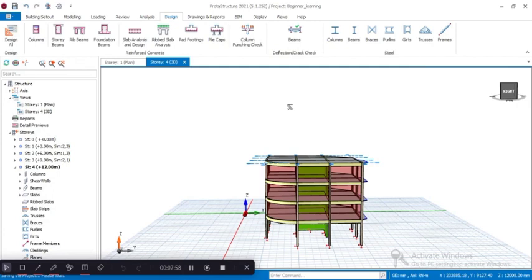This is independent of the general building analysis and can therefore be carried out before or after the general building analysis. To use the moment coefficient method, it is important to set all the slab types correctly in accordance with the tables in BS 8110. This can be done automatically in batch mode by right-clicking on the slab icon in the structural tree and choosing set slab types automatically.